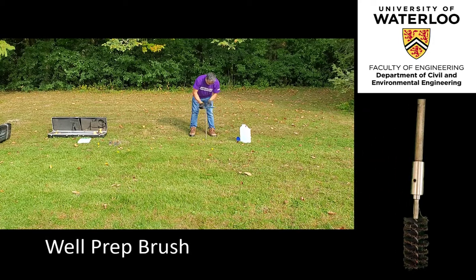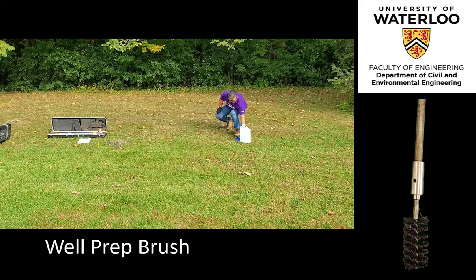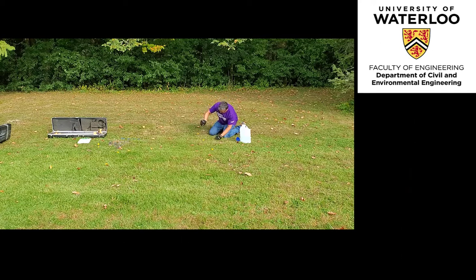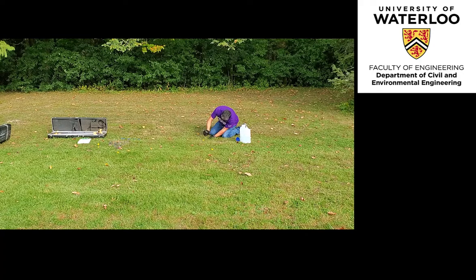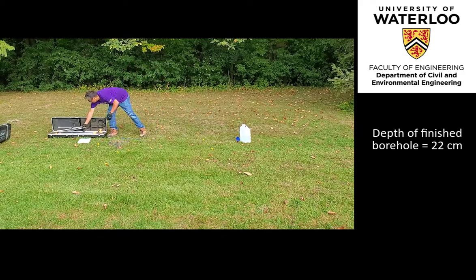To correct for these deficiencies as best as possible, a well-prepped brush is used to scour away the surface layer of the borehole to expose the interstitial spaces and pores to the surrounding porous media for greater in situ representation of the geological media. The depth of the finished borehole is measured, in this case, 22 centimeters. The Guelph Permeameter is now assembled over the borehole.